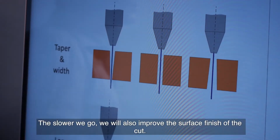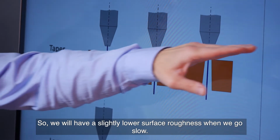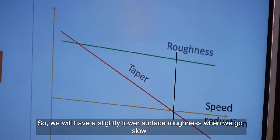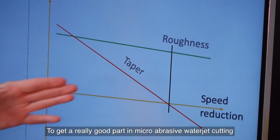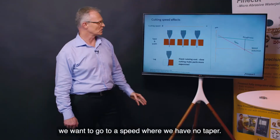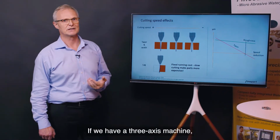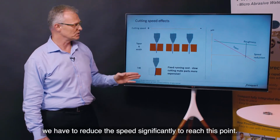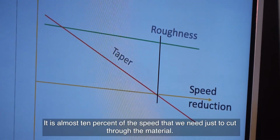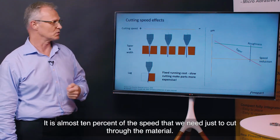The slower we go, we will also improve the cutting finish of the surface, so we will have a slightly lower surface roughness when we go slow. So, say to get a really good part in microabrasive waterjet cutting, we want to go to a speed where we have no taper. If we have a 3-axis machine, we have to reduce the speed significantly to reach this part. It's almost 10% of the speed that we need just to cut through the material.